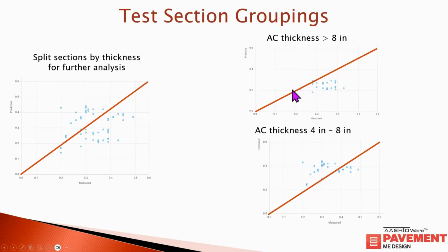So again, do we analyze these differences? If we were to just use this data set, we could probably reduce the bias pretty easily and then have a relatively low residual standard deviation of the residual error. And similarly, we could also calibrate, optimize this grouping of the thicker pavements and come up with, so both these cases, we can reduce the standard error, but again, we're going to have to model these individually. We're going to have a different set of coefficients for the thicker versus thinner pavements.